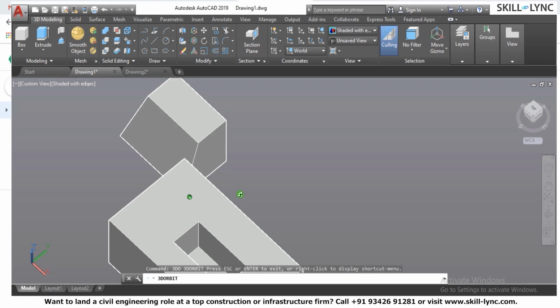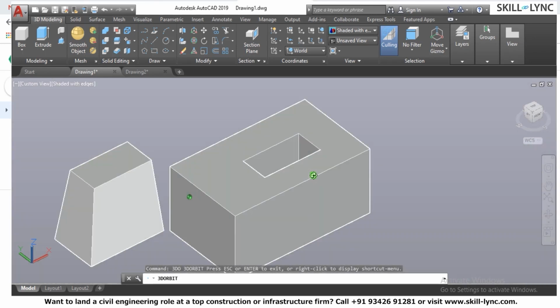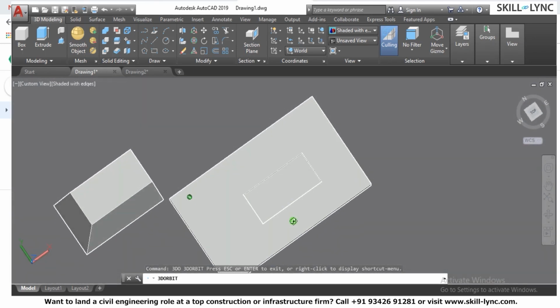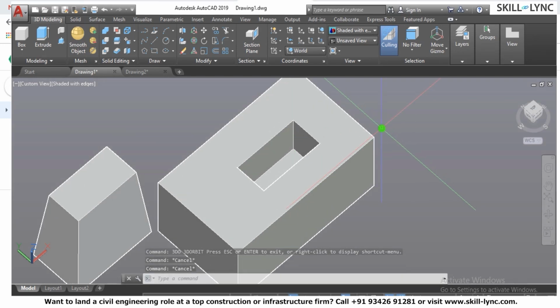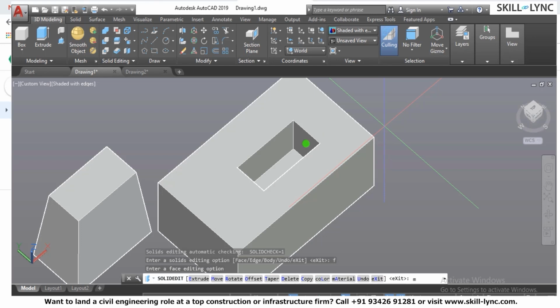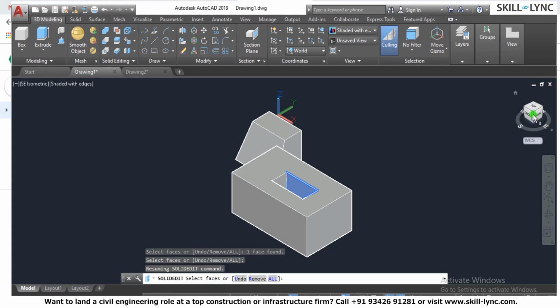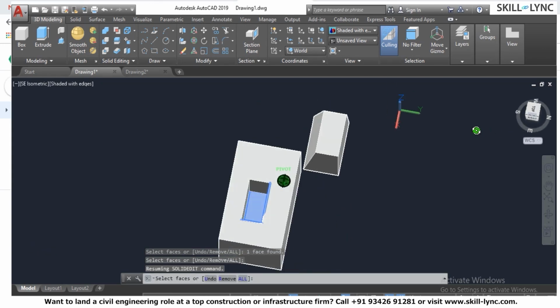Then here I can select the 5 faces to move the slot. So how do I do it? For example, I want to select the 5 faces. So here, I go for solid edit, face, and I have a move option. Select this face, this one, this is fine. And then to select the other faces, just use the view cube tool.